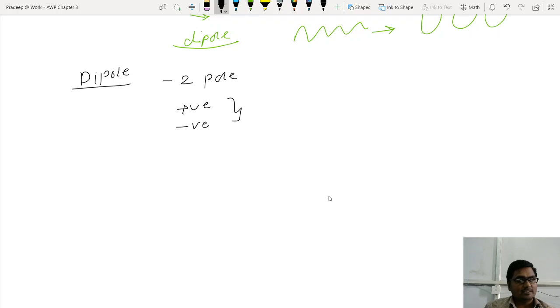Why are the two wires or two poles needed? Because it's a linear type of antenna. In a linear antenna, one is forward, another one is reverse, and it is mandatory. Is it? So when you flare that transmission line by 90 degrees, they form a dipole. Now the question is, how much should the length be?